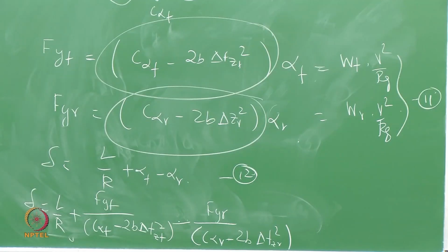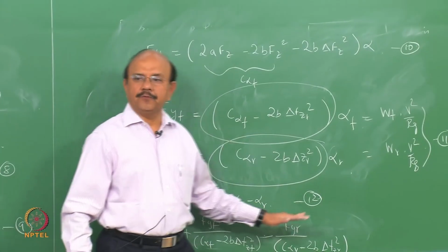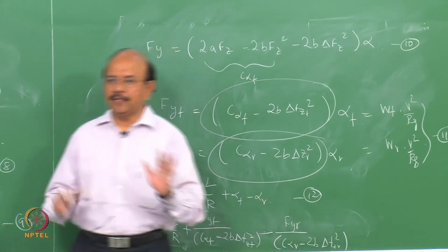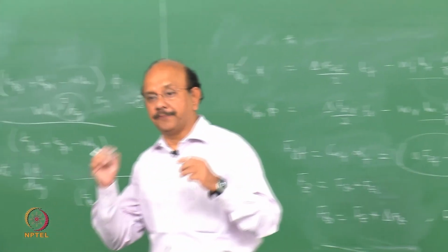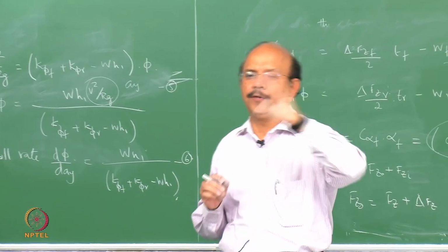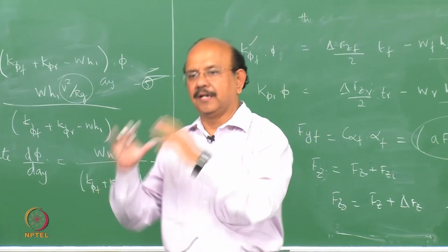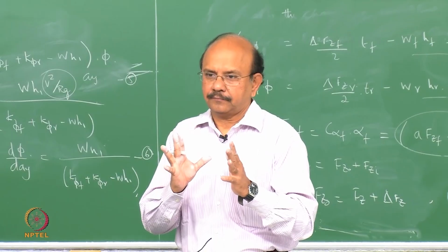Exactly. So in this model, in other words, we are not considering it as 4 tires. This is a simplified model. In practice, in actuality, this won't be the case. What you're saying is absolutely right. So alpha f front outer would be different from alpha f front inner and so on. Now we are getting a gross effect here.